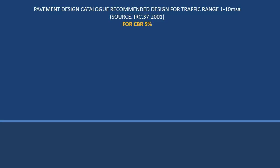This is the pavement design catalog, recommended design for traffic range of 1 to 10 MSA. Our source is IRC 37 2001, and this is for a CBR of 5%. Again, keep in mind that you are going to have different types of catalogs, and you should know which one to use. You have to consider two main things, that is your CBR and your MSA value.